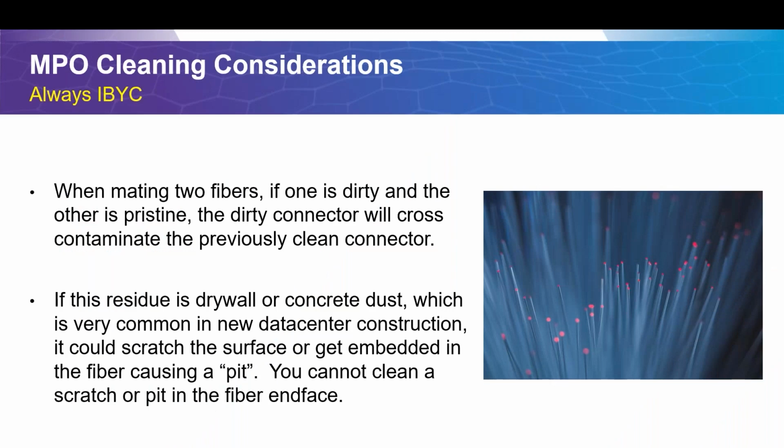When working with a single fiber, just an LC or an SC type connector, it's pretty easy to get that fiber clean. It's pretty easy to inspect it, put your inspection probe on there. If it's dirty, you get your one-click cleaner, you click it, and 99% of the time, at least that's what I've found, you can clean a fiber in LC or SC, or just a single fiber, with one of those click cleaners.